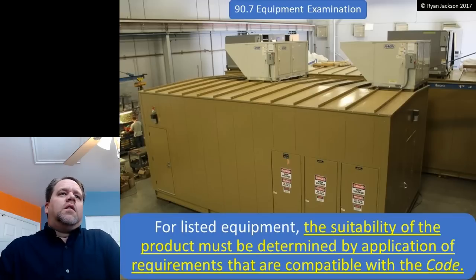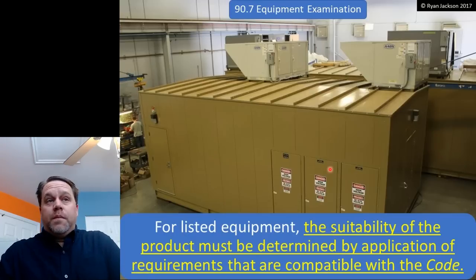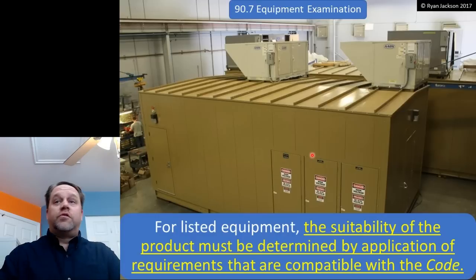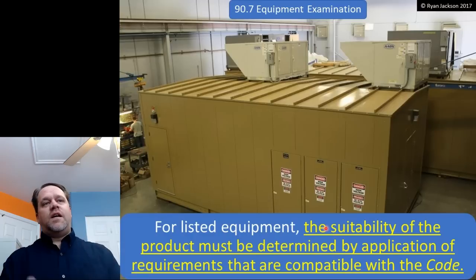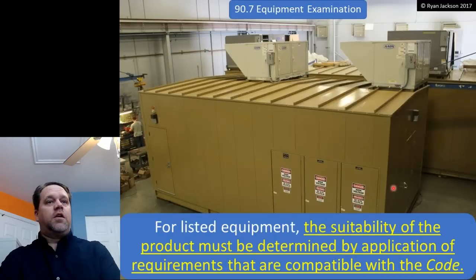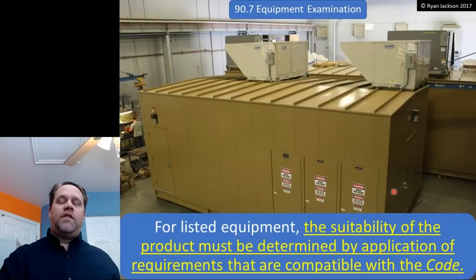What we're looking at here is a listed electrical building. And inside of this, you're going to have a generator and a transformer, a main distribution panel, some panel boards, a motor control center, all sorts of electrical equipment, all pre-wired from the factory, set it in place, done deal. It still has to comply with the code, even though it's listed at the factory. And I don't have to inspect it, except to check for alterations or damage, right? I'm not going to get in there and check the wire size and everything else.